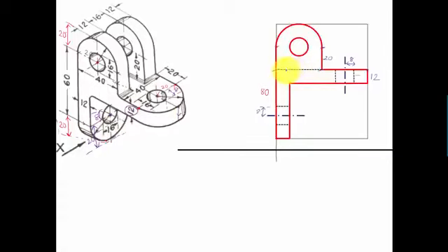We'll now go ahead and make the final top view. Alright guys, this object appears to have a width of 80 millimeters. You know that very well. And as far as this length is concerned, something that you're going to see from the top, this distance, 12 plus 16 is 28, 28 plus 12 is 40. So I'm going to be making a rectangle of 40 by 80, and it should look something like this. This is 40 and this over here is 80.